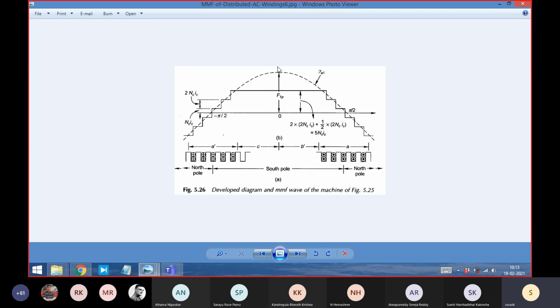A sine wave means a north pole and a south pole. A flux, a rotating magnet. We call it a rotating magnet. North pole and south pole will be moving around. This is happening anywhere there is a three-phase winding, and anywhere you are able to create currents of that nature, which are time shifted.